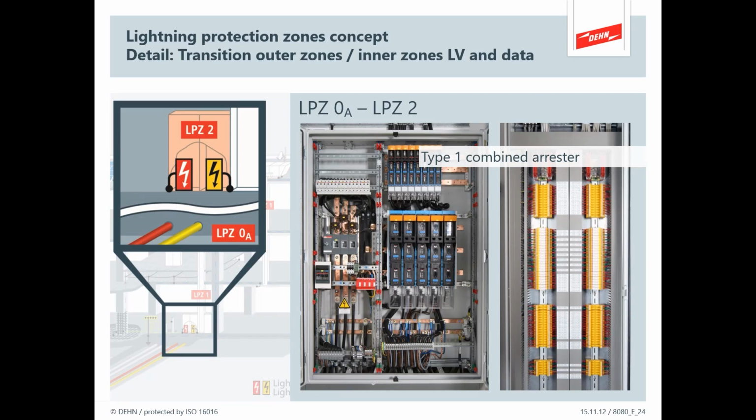And the thing with some of these slides is that the appearance of the SPD may change because of the application, so don't get too hung up on that. And you'll also see that, again, as I said before, it's not from LPZ0 into 1. The metal box is a further zone within the volume of the building.